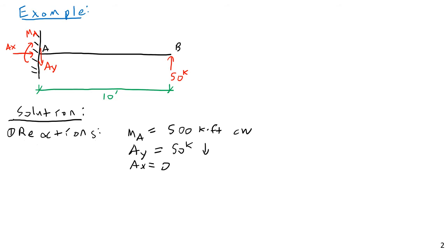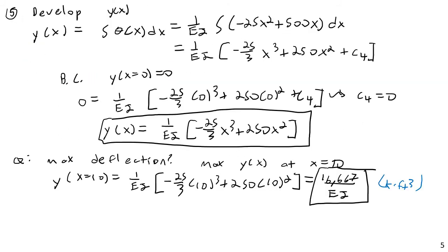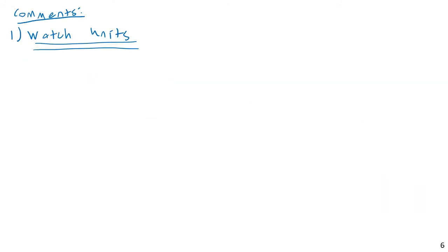I will automatically convert the beam length into inches if I'm doing it in inches, or if I'm doing metric, I'll automatically convert it to meters. Basically, convert it to whatever units your moment of inertia and your modulus of elasticity already are in, and that way you can avoid a whole bunch of headaches with your units, because otherwise you are going to get some weird answers. I can pretty much guarantee you that somebody on the exam coming up is going to have a unit error or two, but it happens.